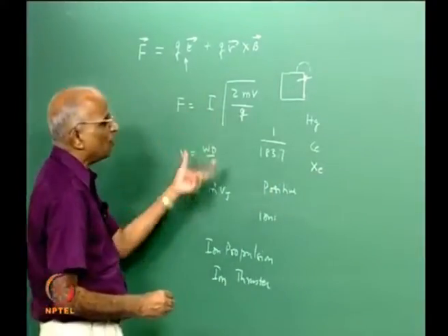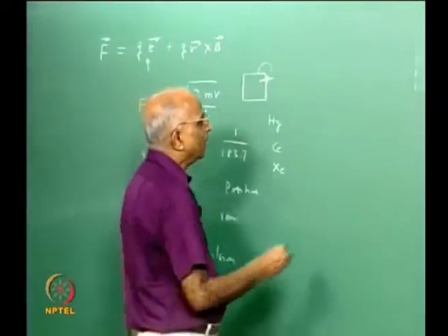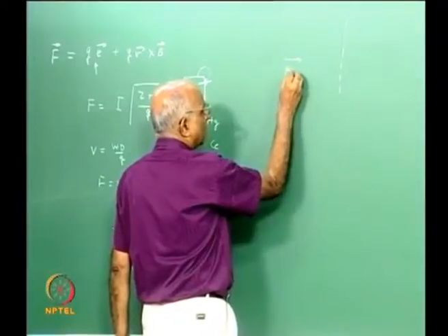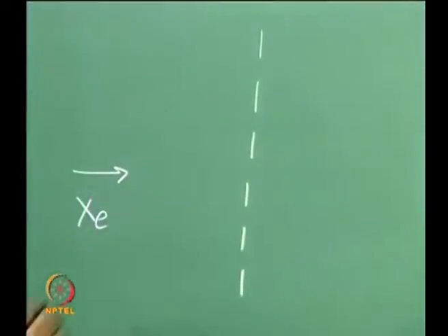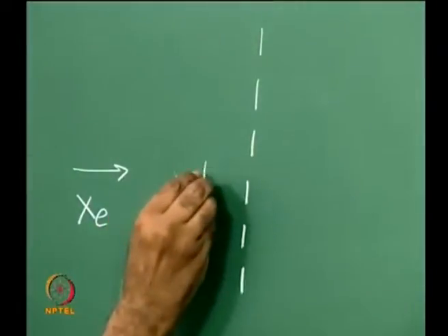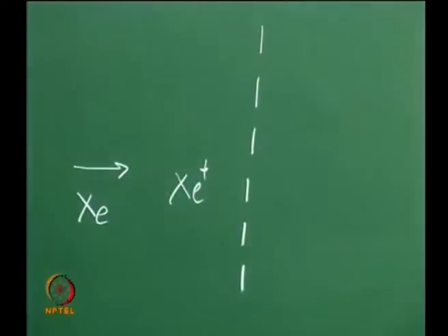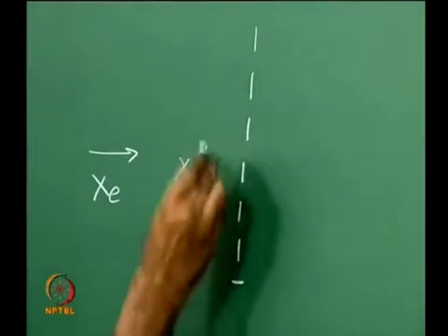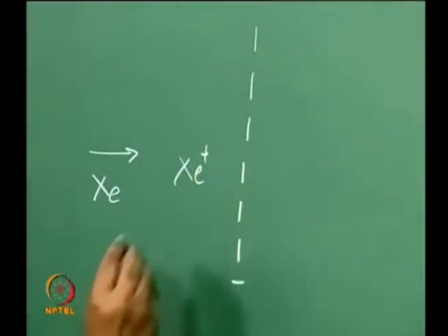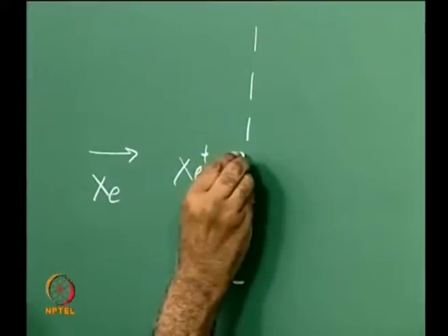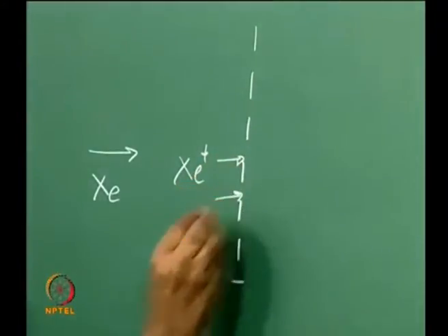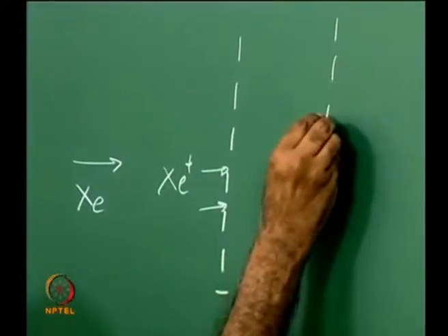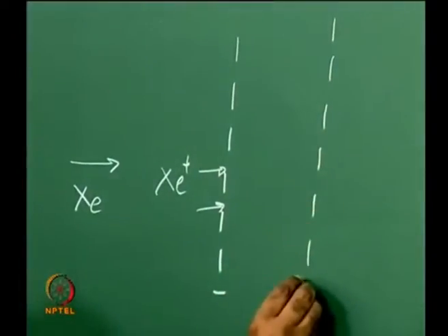Therefore how will the construction of an electrostatic rocket look? Well, I need to pump in this particular xenon gas, I need to generate positive ions of xenon, and then maybe I put something like a negative grid over here, something like a screen which is negative, such that it will attract the positive ions towards it, and again I put another screen over here which is still more negative.